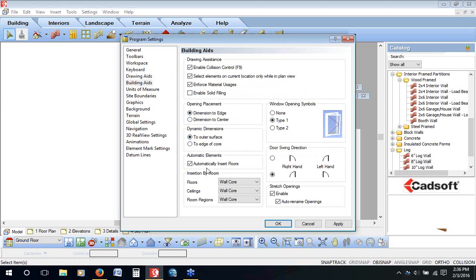In the software, as soon as I draw my building, a floor is automatically put inside the room. Its default selection is a hardwood floor. You might have noticed if you've drawn a room, hey, there's already a hardwood floor in there. How handy is that? And as I subdivide the house into rooms, they'll automatically be separated into separate floors. That's our automatic floor tool that's doing that. Those floors are meant for the finished surface only. It's not part of the structural floor. So if you're happy with the automatic floor and the surface that it's giving you, you can keep that checked.